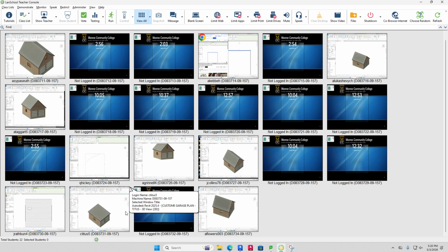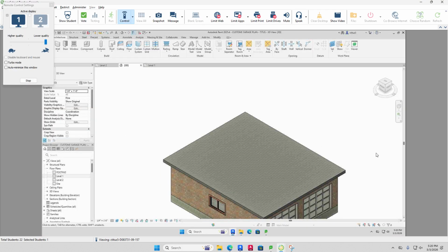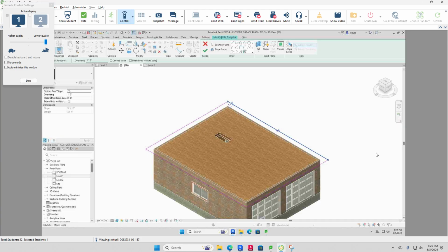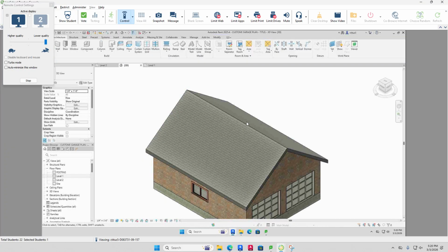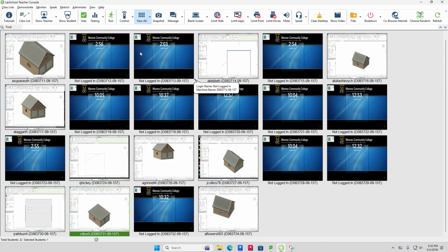Okay, so what you want to do, Kanaya, is just go ahead and double click on the roof. Now grab the line to the far right, click on it. Yep, and then up on the top on your ribbon, it says define slope right there, perfect. And then you want to do it for the left side, use define slope there, and hit your green check mark, and you're good to go. Looks good, looks great. Okay, so now it looks like we pretty much all have that in place.